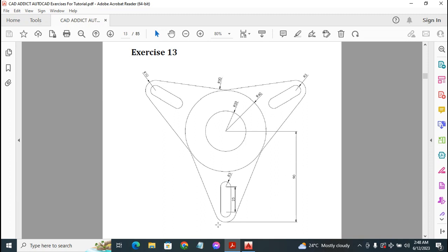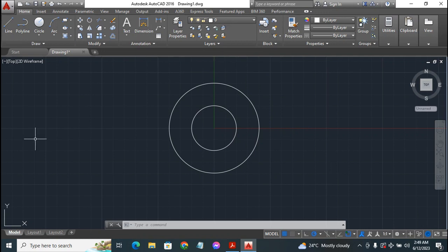millimeters. So I'm going to draw in some construction lines. I'm going to get a horizontal construction line that will cut across our circle right at the center, and I'll set it at a distance of 90. Then we'll start off from there. Back to CAD, I'll go to the layers ribbon, click on the drop-down of the layers ribbon, select construct 1. Then I'll go to the draw ribbon, click on the drop-down of the draw ribbon, then I'll click on